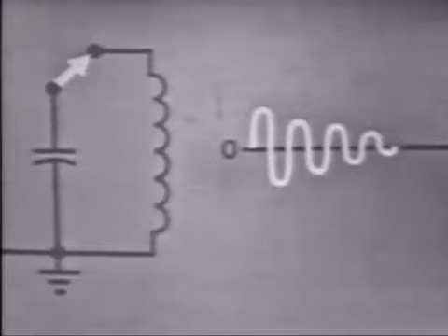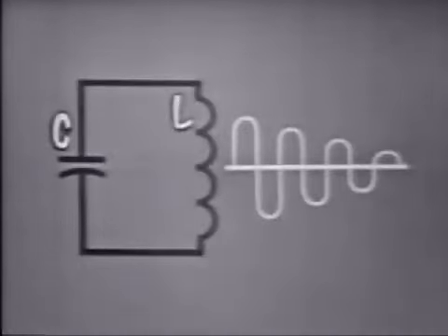The current waveform generated by the LC circuit looks very much like the graph of our mechanical oscillator. Why did the amplitude of the oscillations decrease? In the mechanical oscillator, inherent resistance or friction. Now, if we apply this reasoning to the LC circuit, it's obvious that the decrease in amplitude is caused by internal circuit resistance. That is, the resistance of the wire finally dissipates all of the energy. Now, we'll represent this resistance here.